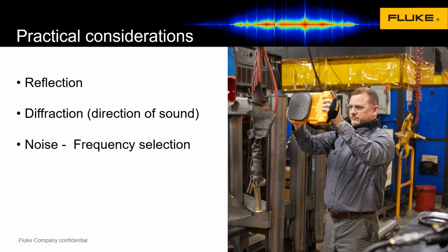It's almost like, hey, I have a clue. I'm going to follow the trail that clue gave me and find out the exact location of the air leak. When you're using traditional ultrasonic tools, you're going to see all of those ultrasonic reflections on the floor as well, but it can be a lot more challenging because you don't have a visible image of exactly where it's coming from.